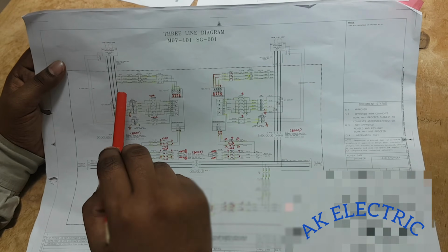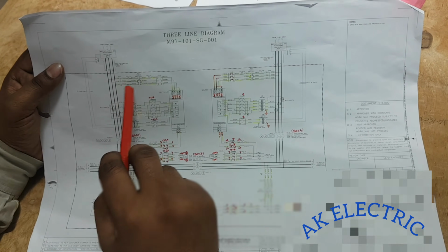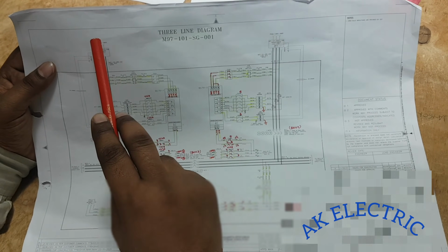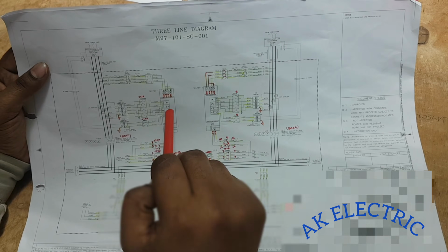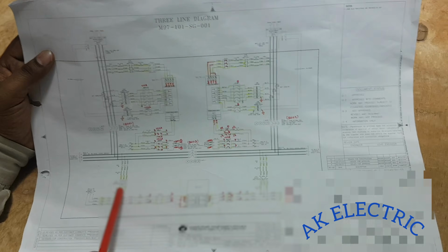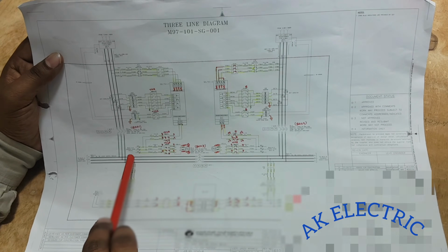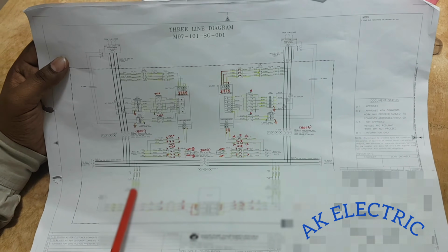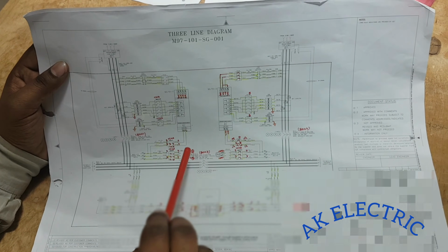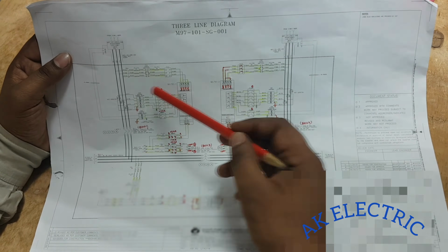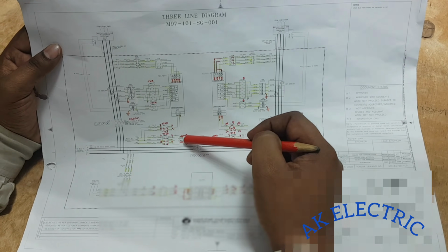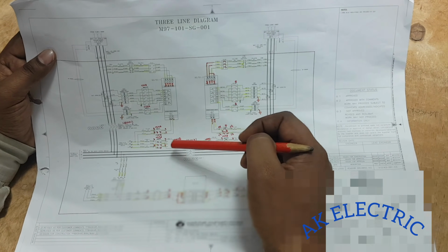See here, this bus will be connected to this VT. Okay, this VT will be connected to this relay. So once you give the power supply, the voltage which is shown in this relay is called as line voltage. Okay, for bus voltage, from bus we will connect some wires to this VT, and this VT will go to here, and in voltmeter it will show bus voltage. So relay will show the line voltage. Once breaker closed, after bus energized, bus voltage will show in this voltmeter. This we will see in real time.